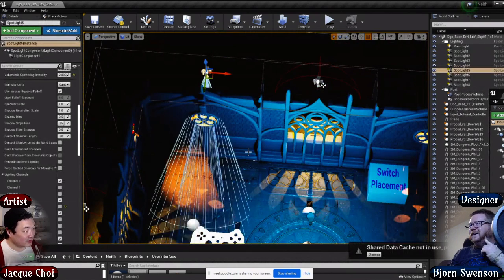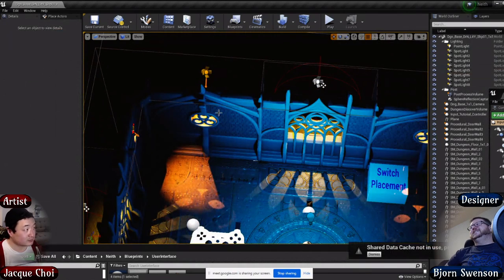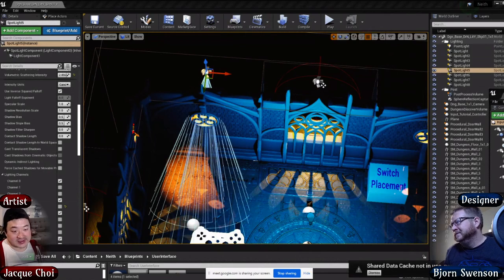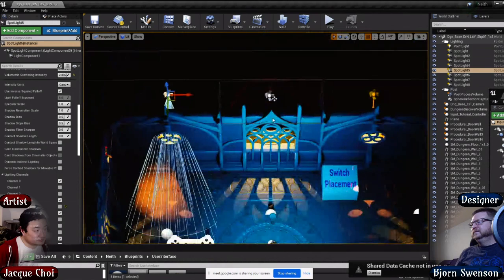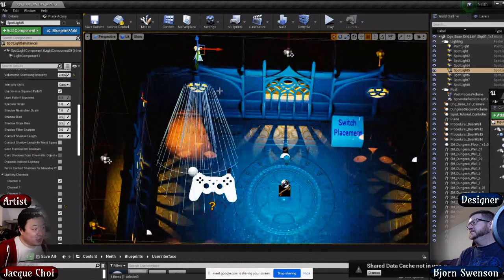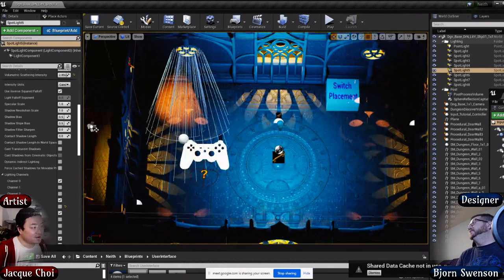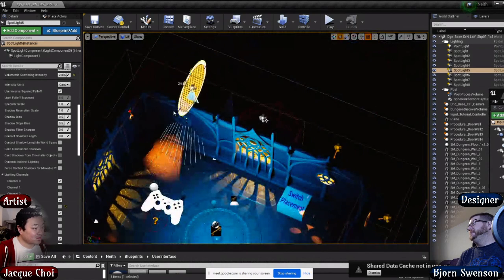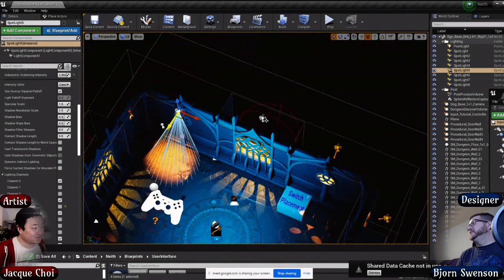Under lighting, allow static lighting is disabled. So that's why you can't bake lighting. Okay. Oh well, I'll figure something out. That makes sense. All right, so we'll come up with a more elegant solution for something like this. I realize I actually built these walls with these windows in mind to do that. So if we're not going to do that, maybe I should just seal up the window and have another light source, one of these things hopping out on top and lowering the.